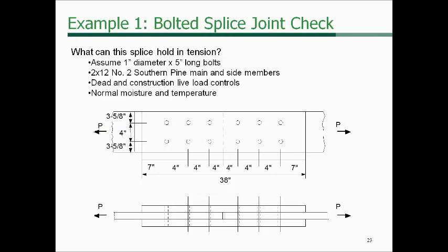When we look at the net section properties a little bit later on, that can affect the outcome, and so there may be cases where, again, spreading out the fasteners in a lot of cases is better than locating them all real close together. But you may be constrained by the depth of the wood member in certain cases or the length of the splice that you have available. So those are all part of the consideration in connection design,